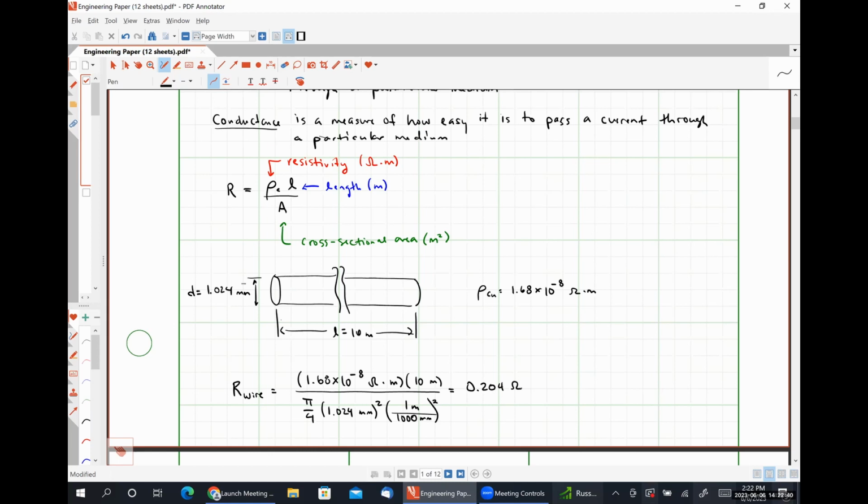The only time you're ever really going to need to pay attention to the resistance of a wire is when that wire is going to be carrying a very large amount of current. Because if you pass a large amount of current, even through a small resistor, you can still see an appreciable voltage drop.